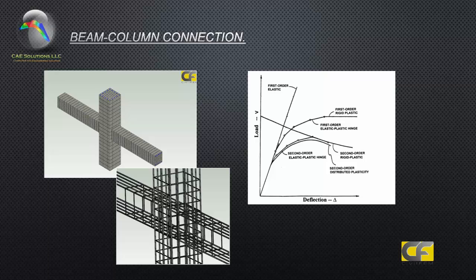And we also have, in this curve, second order analysis, where we have a loss of rigidity and a loss of strength. As the internal forces are magnified and the lateral stiffness is decreased, a smaller portion of the structure capacity remains available to sustain lateral loads, leading to a reduction of the effective lateral strength. So we have the behavior of the elastic first order analysis, the behavior which is modeled with the elastic hinge, and